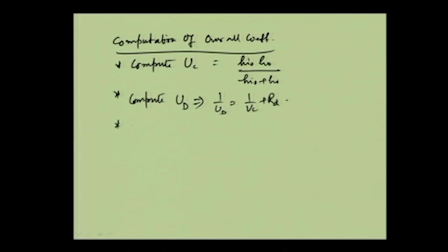Then compute A, the area of heat transfer, from Q is equal to U A delta T Lm, log mean temperature difference.